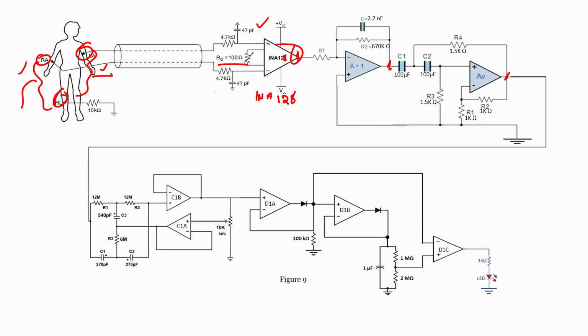So we will try to see the effect of baseline wandering in the system. The baseline wandering is nothing but the signal always wandering with respect to the baseline. This is because of respiration; during the respiration of our breath, it creates some kind of noise in the system, which will be somewhere lesser than 0.5 Hz. Since we are using a high pass filter, after passing through it we can see the complete removal of our baseline wandering, and even motion artifacts, which are in the same range, will be completely eliminated when we pass through this particular system.